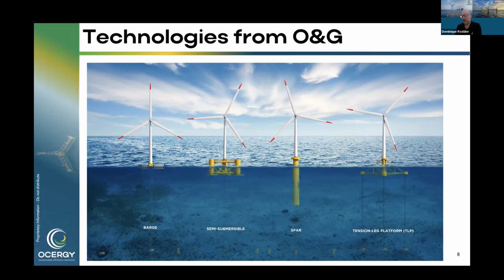Spars are only good in Norway, in fjords, because we want to install the turbine at the site. So for Utsira, we'll propose a spar, but that's really specific to fjords. And with tension leg platforms, you're paying much more than you need. It's an economics problem. If you don't need the stability, you don't have to pay for those big offshore operations.